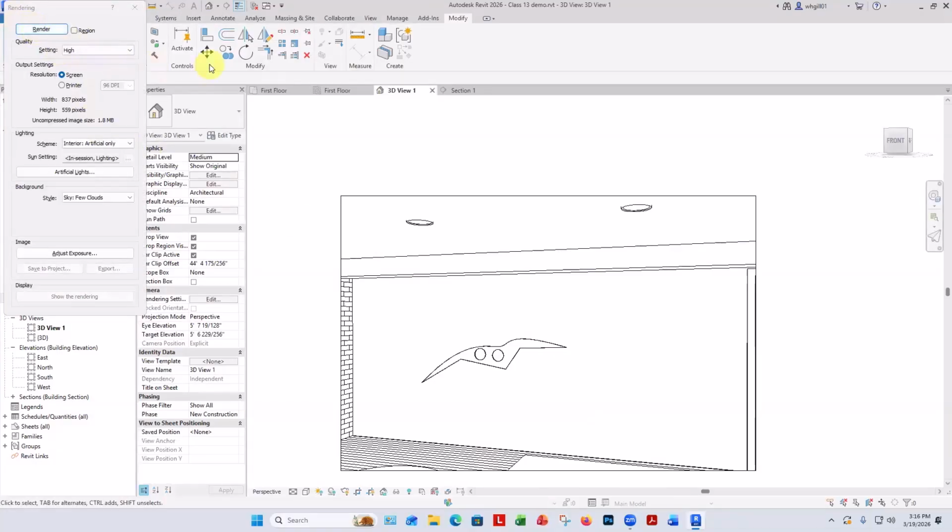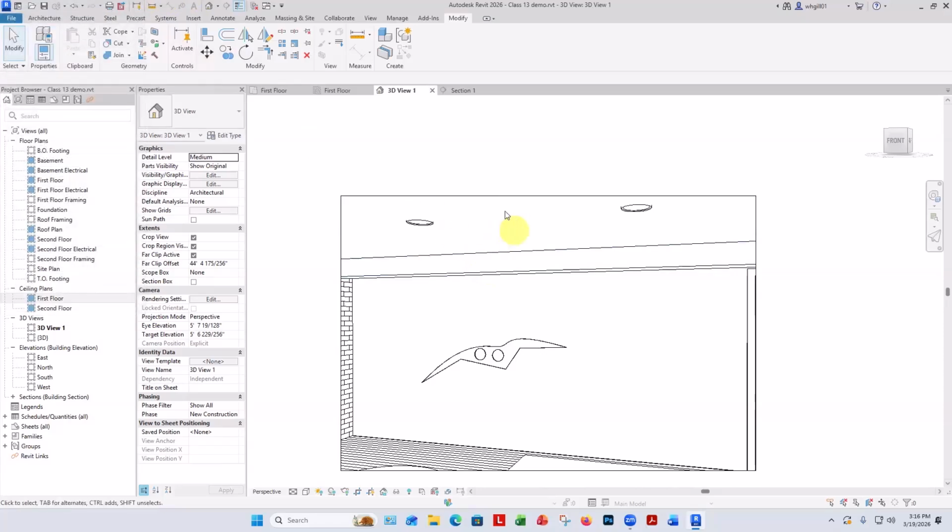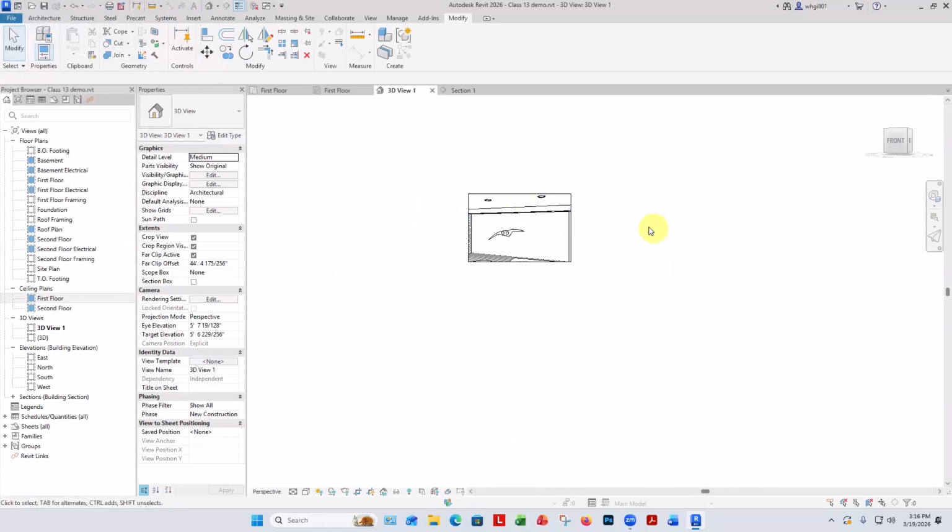Go. Oh, here's something else. When you're rendering on the desktop, it's sort of nice to see these things big, but if you make them small, they'll render a lot faster. If you make it half the size, that's a quarter of the area, so a quarter as many pixels, so it'll happen in a quarter of the time. So let me just try it like this and see how this goes.